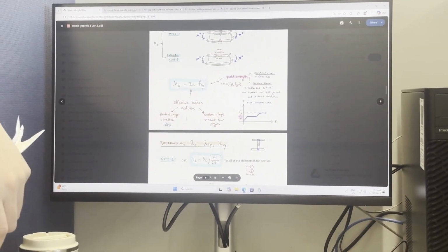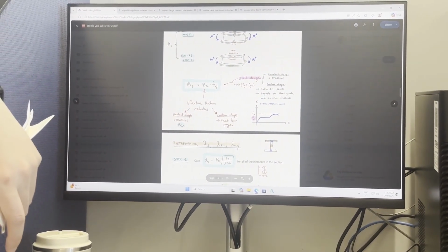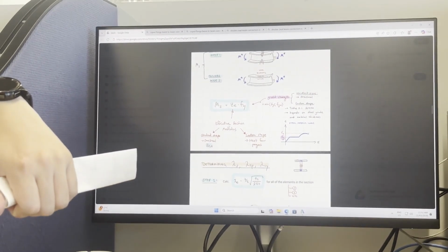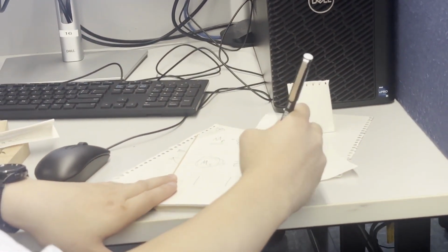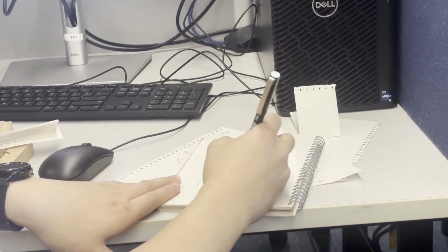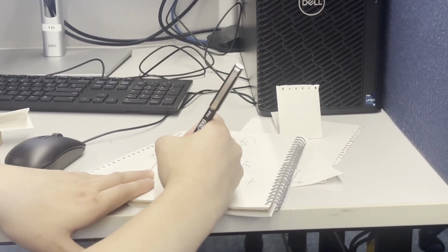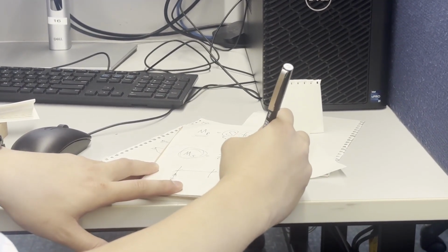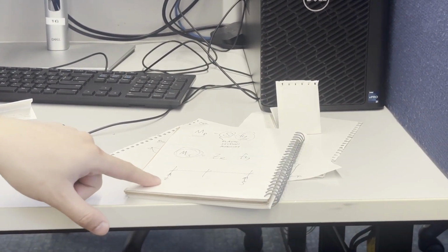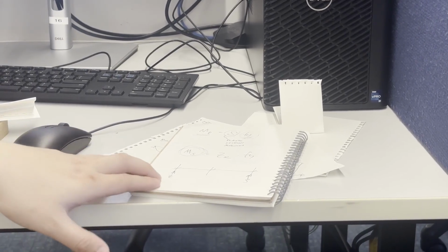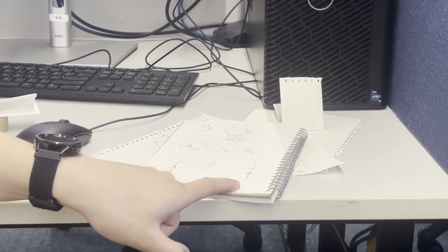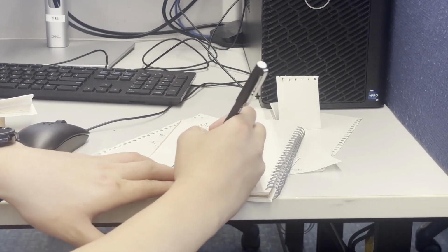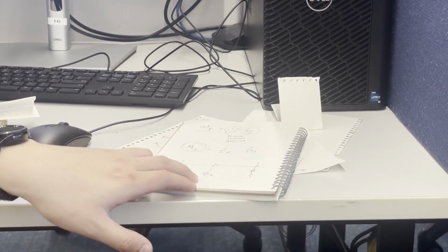So why do we multiply by Ze, the effective section modulus? Why do we multiply by it? If you imagine it as a number line, over here we've got Z, and over here we have S. Z is whatever elastic section modulus your shape has, and S is the plastic section modulus. Ze is some number in between.